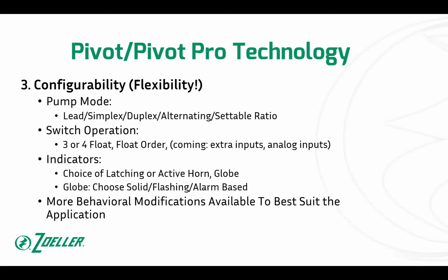And then the last mode, which is the first one listed there, lead. What's that? Well, on old panels, when you wanted what's called a lead lag operation, that meant you wanted one pump to always be kind of the lead pump, and the lag pump, the second pump, would never turn on unless the lag float came up.